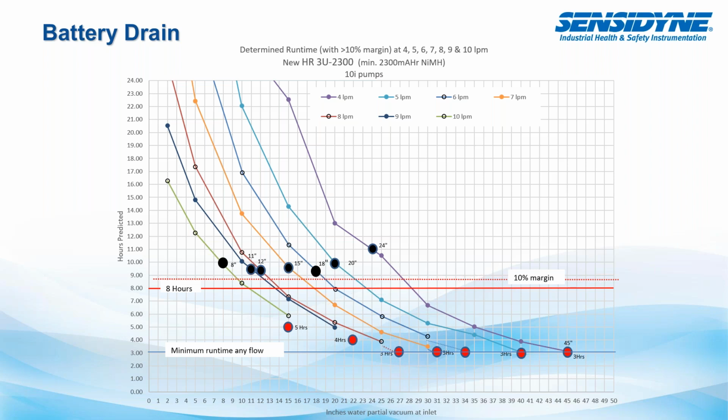So this is how we ended up getting what is the most back pressure that pump could handle at 8 hours. And we're able to actually calculate a curve to look at each back pressure to get that information. And then of course we set a 10% margin as a buffer to make sure that, again, you're not reaching that fault within your sampling event.